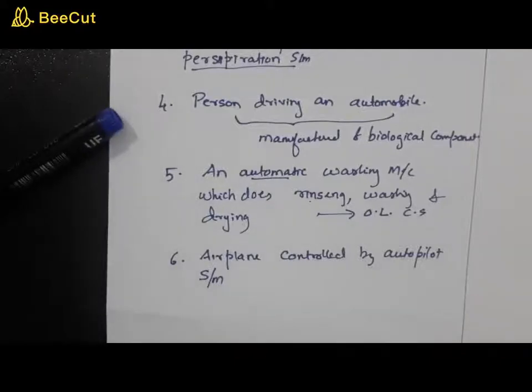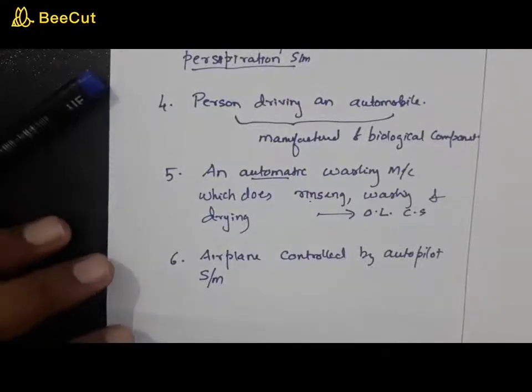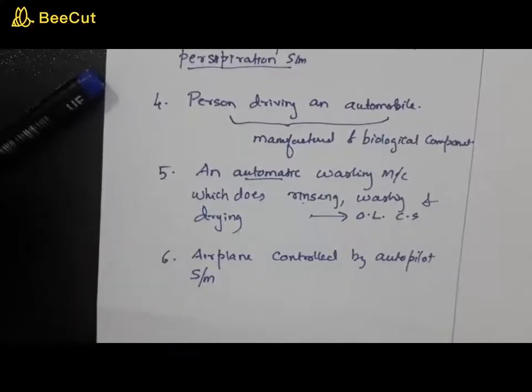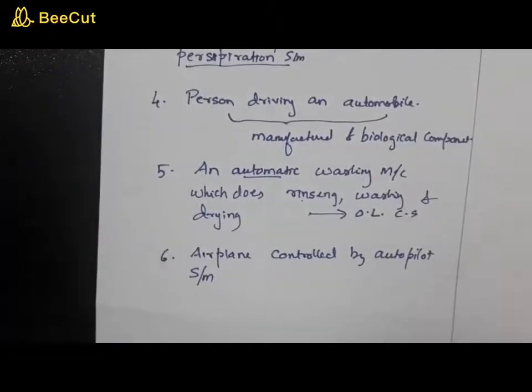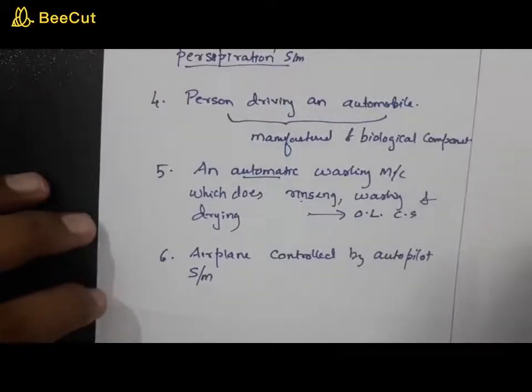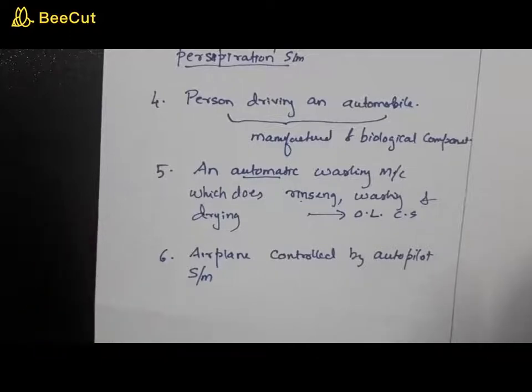Now what happens? The compressor will be active till it achieves the temperature of 24 degrees Celsius. As it achieves 24 degrees Celsius, the compressor will be turned off automatically, and the air conditioning system will be checking the temperature of the room again and again.